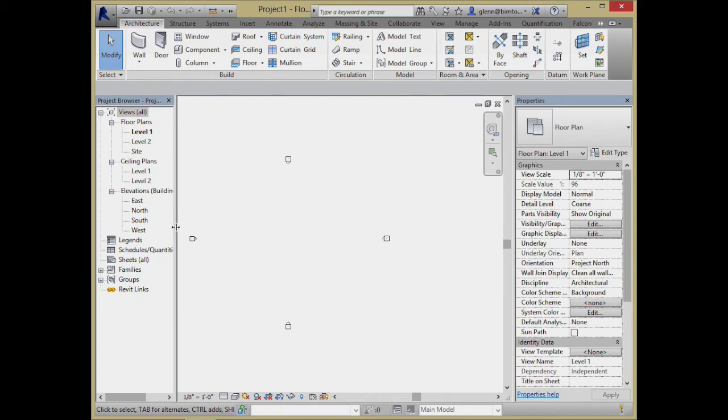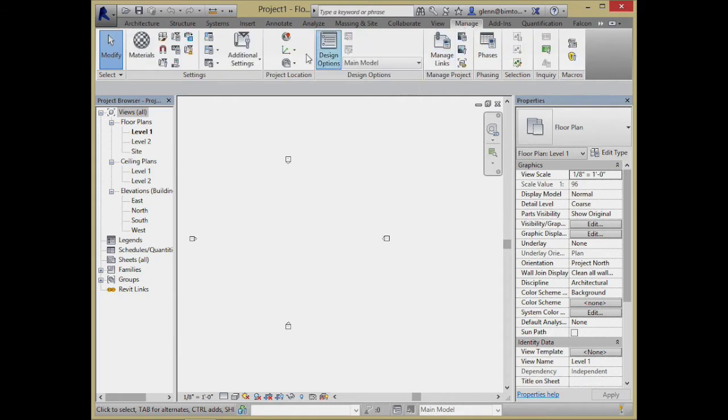So what we are going to do is ultimately choose a location for our building. And for this building, I'll go with most anything. How about for today, we'll just put it as though it's here on the campus, something like that. That's relatively easy to do. So to start with locating our building, go to Manage, and we'll choose a project location.